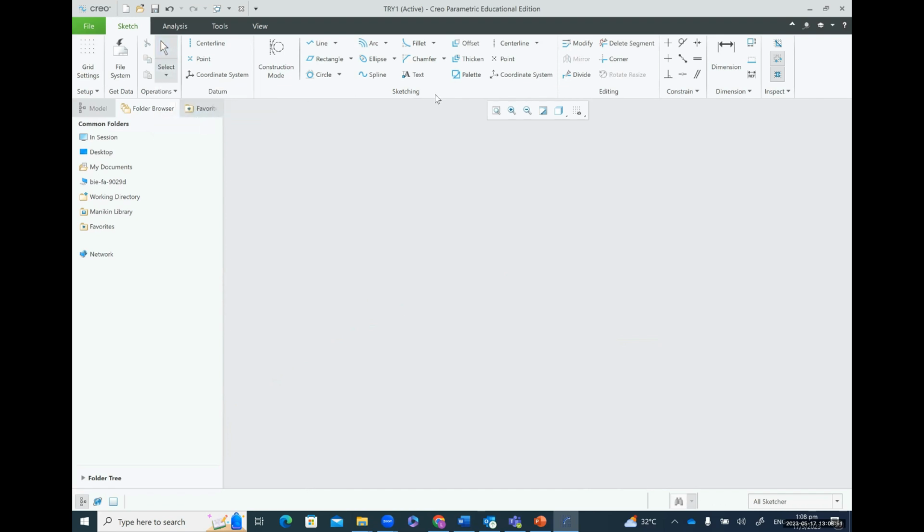So this is fine. Now, how about the fillet and the chamfer? These fillets and chamfers require two lines. Let me demonstrate the function of the fillet and chamfer. Go to the line tool, and then maybe you make a rectangle. Then you click on fillet. You make a round corner between these two lines. First click on one line, and then click on another line. Then it makes a curve, a round shape at the corner. That is the fillet.